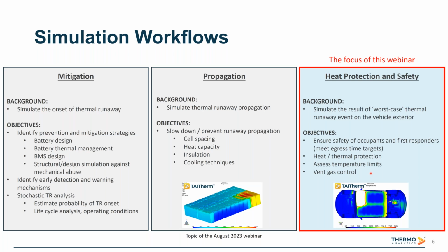So you saw in the previous video what venting looks like, as the pressure in the battery pack increases as the cells continue to vent, releasing some of that to avoid explosion. And that's impinging on some of these components in the underbody of the vehicle. Okay, so we're trying to control that vent gas and identify any risks posed of impingement onto hazardous components.